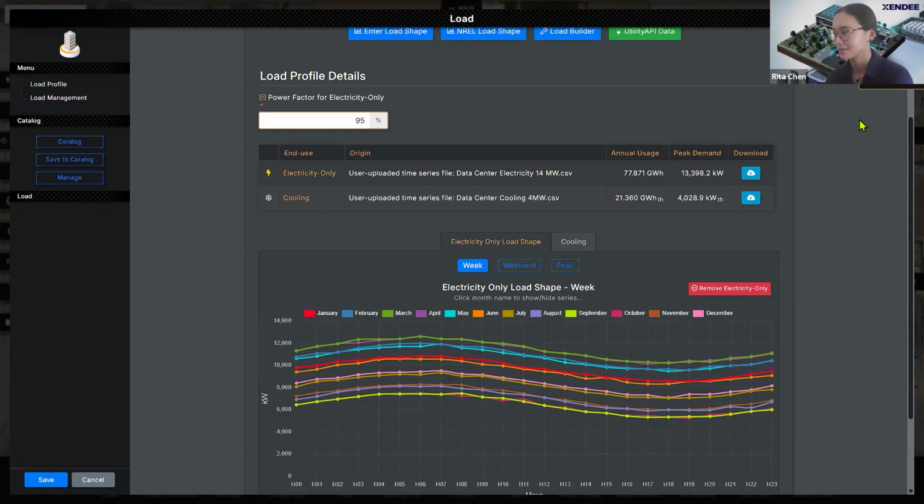And let me add something here, Rita, because what Rita is saying is actually a point that we didn't really emphasize on Monday. You don't want to mix the cooling profile with the electricity profile because it reduces your flexibility in the system. And this is why we split this. You don't have to do it, but if you have the data, maybe you're metering the node in reality, which has the electric chiller, then you know your electric demand for the chiller.